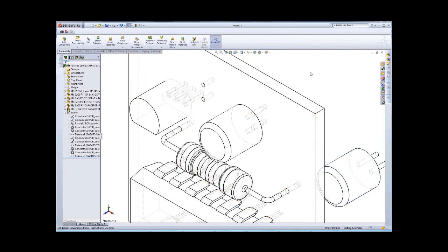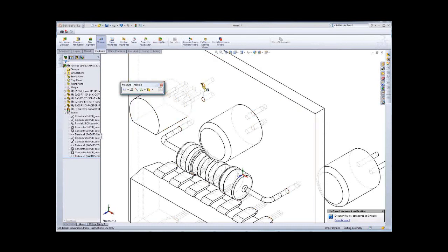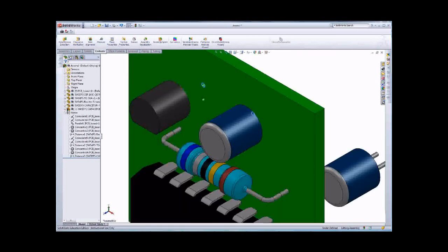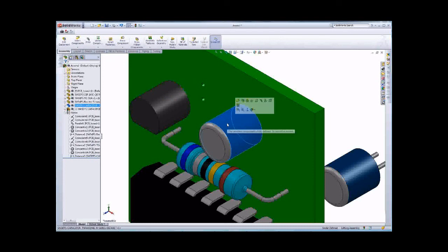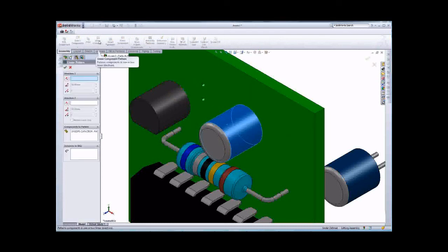You can go to that one and then using evaluate, measure the hole distance, that one to that one. You can see the center distance is 8 millimeters. So when I use the linear pattern, I just select that component, click into the component capacitor, and then using linear pattern, the direction is that one, the correct direction, because you can reverse the direction or you can just make the correct one.